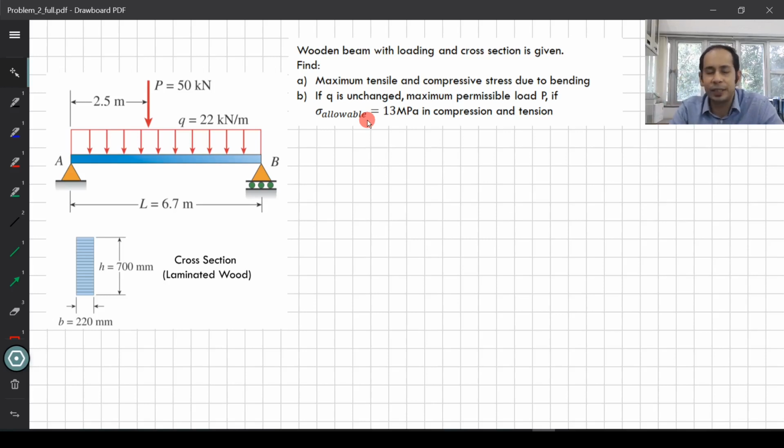So technically it is not a case of uniform bending, but as we discussed, even for non-uniform bending, or bending which is not quote unquote simple bending, if you take a very small chunk near where the maximum occurs, it can be approximated that the moment is constant at that small location, so the bending formula or the flexure formula we derived still holds good.